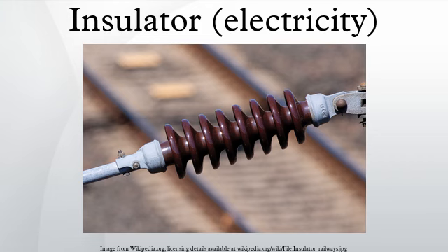Flexible insulating materials such as PVC are used to insulate the circuit and prevent human contact with a live wire having voltage of 600 volts or less. Alternative materials are likely to become increasingly used due to EU safety and environmental legislation making PVC less economic. Class 1 and Class 2 insulation.